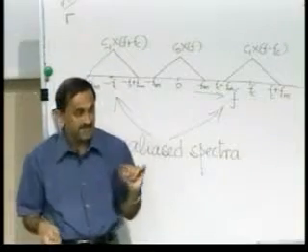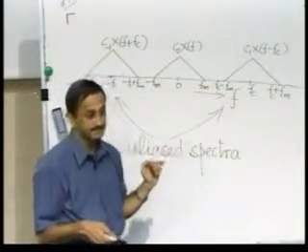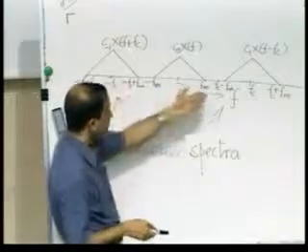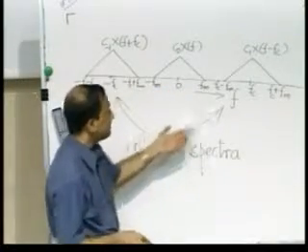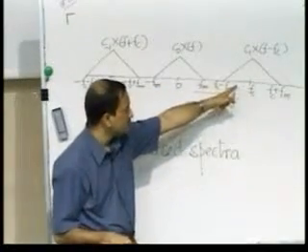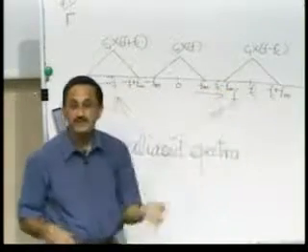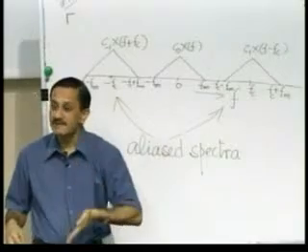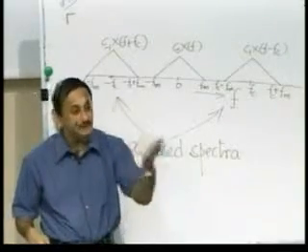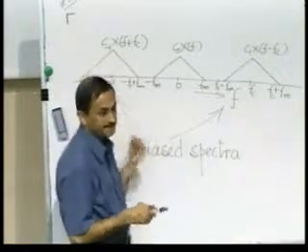We are forcibly introducing aliasing. Is the waveform shape also changing? The waveform shape, of course, would change. In fact, if you made a band pass filter around 3 Fc, it would be equivalent to multiplying the original waveform by a sine wave of frequency 3 times Fc, right?